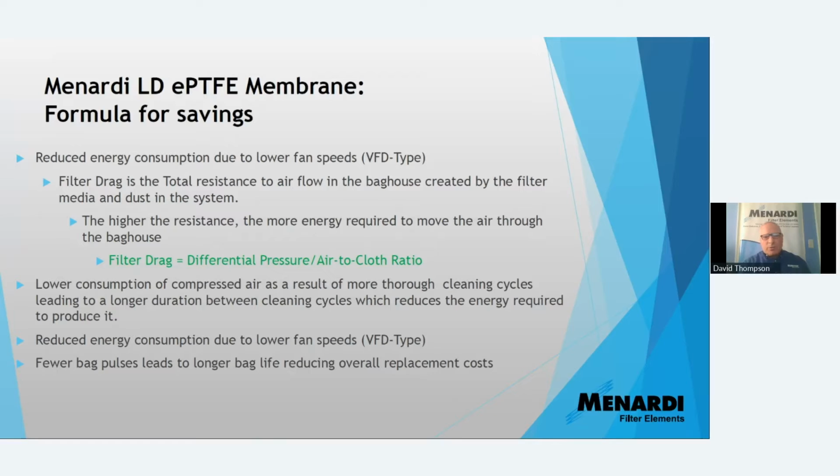So what we try to do with our LD membrane is to conserve energy by operating your fans more efficiently, producing less compressed air because you don't have to do back pulses frequently, and then saving overall cost in the unit by reducing energy costs. And in the end, reducing the wear on the bags, because typically most bags wear out from the inside just from pulsing or over pulsing.